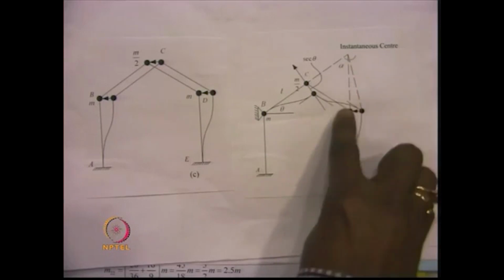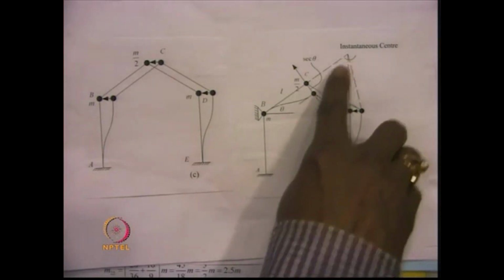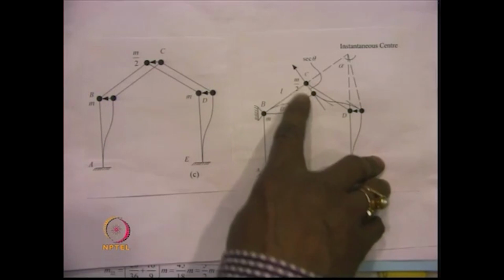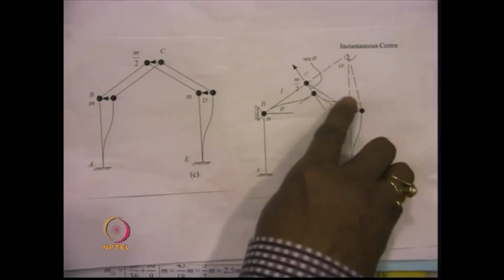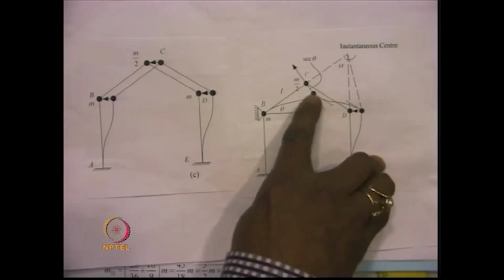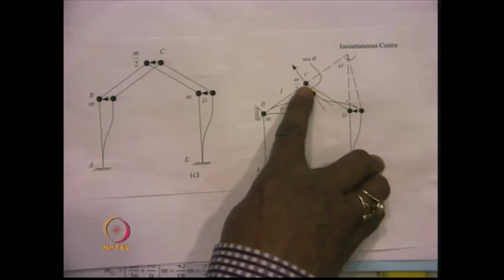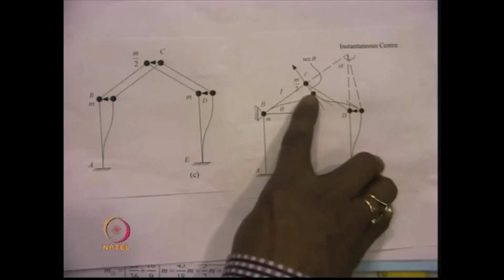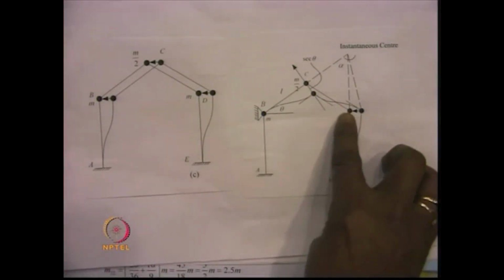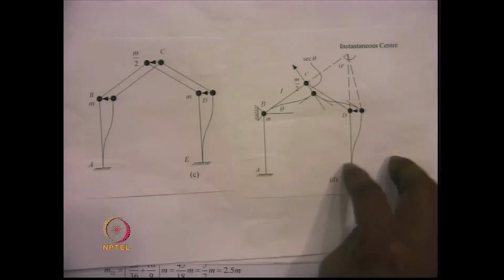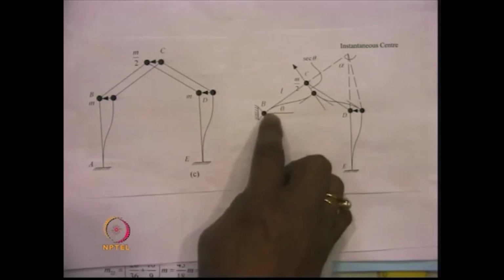This point will move perpendicular to this member according to the small displacement theory, and they do not undergo any change in length because they are moving perpendicular to the members. If two sides do not undergo any change in length, then the third side also will not undergo any change. Therefore, this length which was there initially, the same length remains over here. So, the condition of inextensibility is maintained. Similarly, since this member is moving perpendicular to this member, there is no change in length, and also since this member is moving perpendicular to it, there is no change in length of this member.